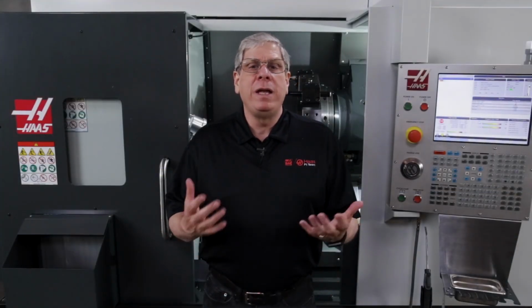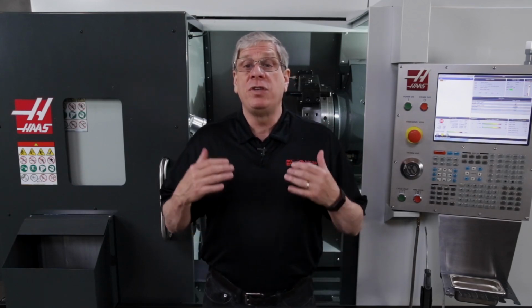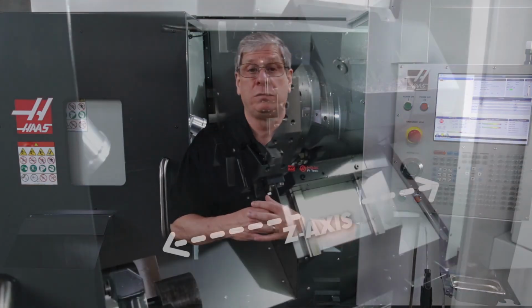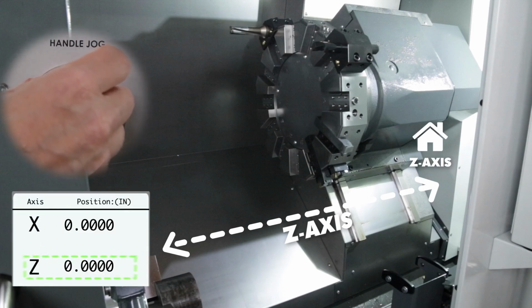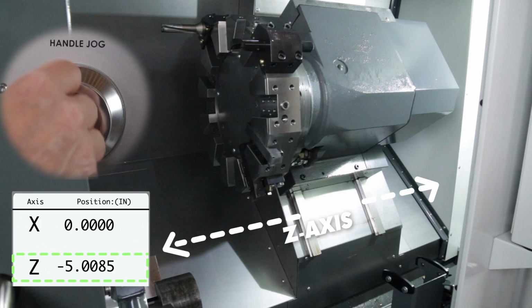We won't go any more in-depth on offsets for now. Just understand that until these numbers are entered correctly, the machine doesn't know the location of the part or the tool. As we saw earlier when we were using the machine coordinate system, as we move away from our home or zero location, the machine position increases in the negative direction.